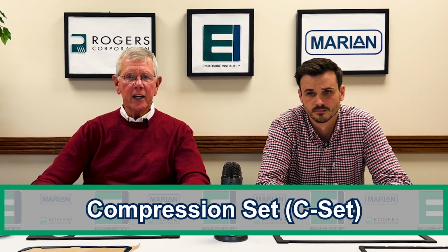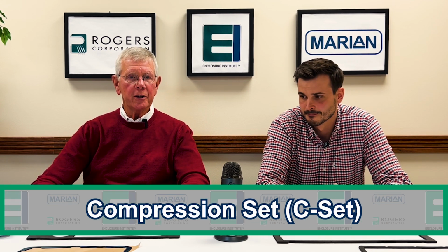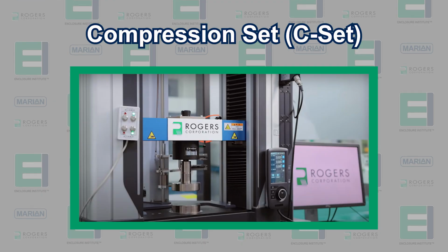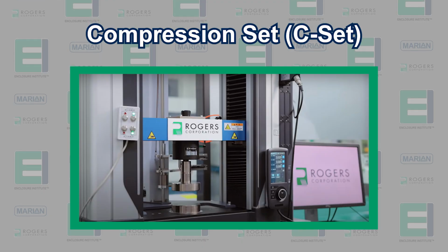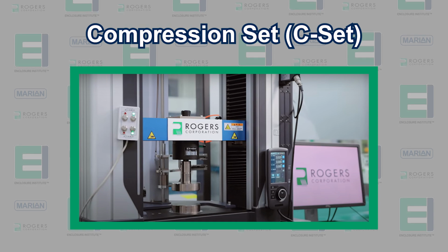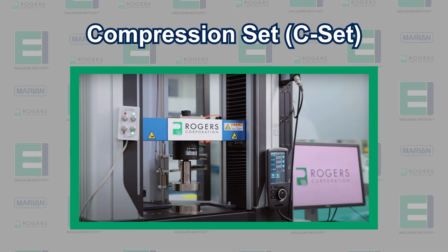The compression set, or C-set value of a foam material is also determined by ASTM and other test methods. In these tests, a specimen is compressed to a given percentage of thickness and maintained in that compression over a prescribed amount of time at a given temperature. Some tests call for the specimen to be held in compression for a long period of time, like 24 or 72 hours. Others call for repeated compressions, varying the frequency and duration of each compression over a period of time.